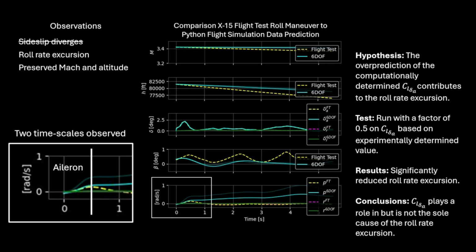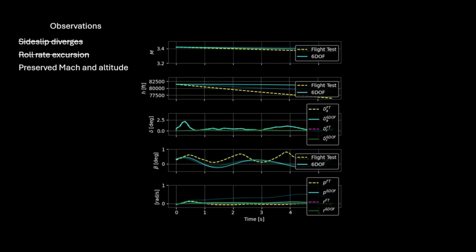Instead of roll rate subsiding, it slightly increases. This is evidence that our system is underdamped. Somehow, the flight test exhibited significantly more damping in roll than our simulation is providing. This could be due to yet an unknown bug in the sim affecting the roll channel, or an issue with reporting the flight test data, or both.